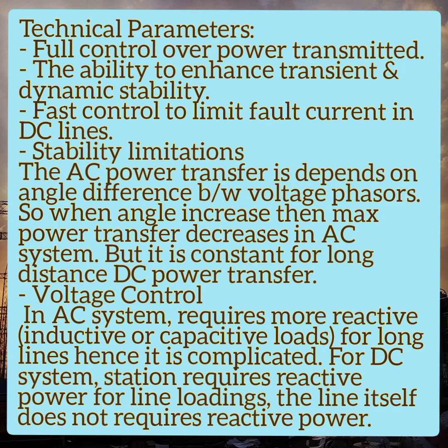Then stability limitations. Normally the AC power transfer depends on the angle difference between the voltage phases. So when the angle increases, the maximum power transfer will get reduced in an AC system. But in DC, it is a long distance DC power, and it is also constant.